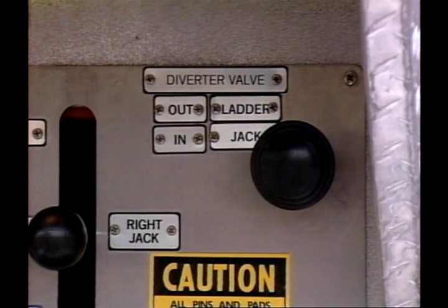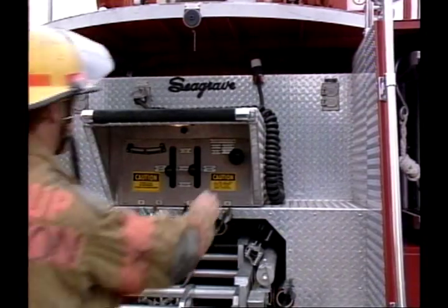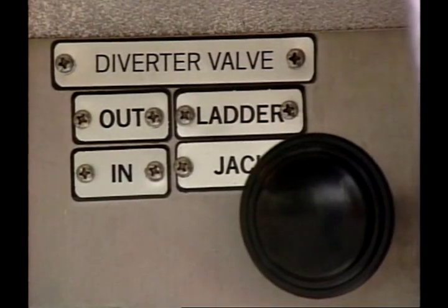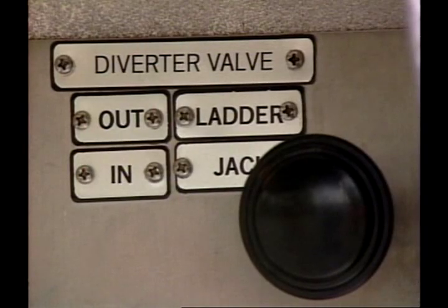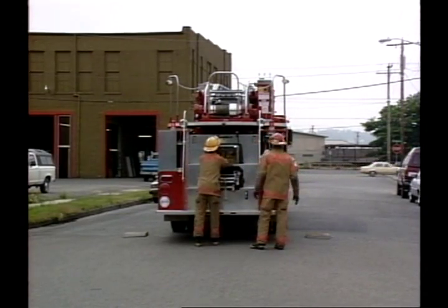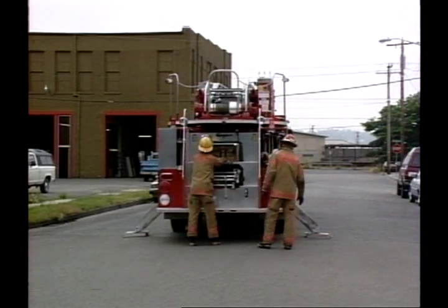Once you have completed the preliminary checks, you are ready to operate the selector valve that will provide hydraulic power to the stabilizing system. The operation of the selector valve varies with the manufacturer. If your apparatus has a manual selector control, it will be clearly marked to indicate the position for each operation. The engine speed is automatically regulated to provide enough power for the operation.